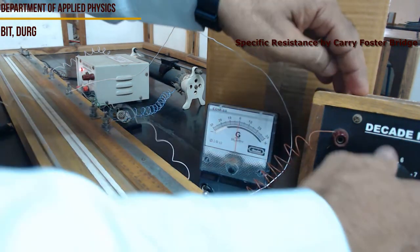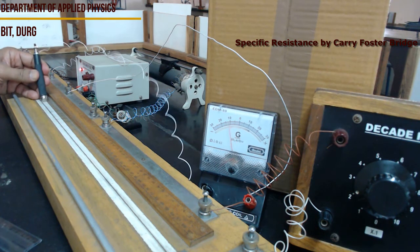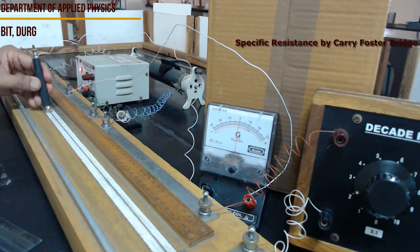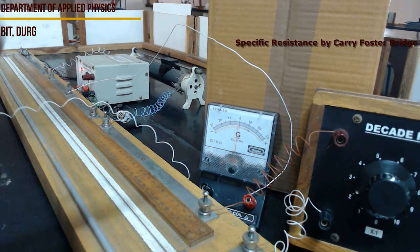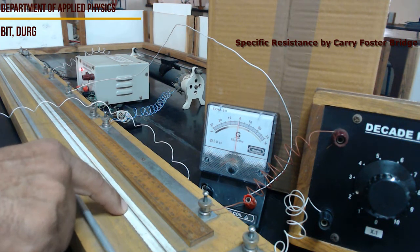Similarly, I increase the resistance to 0.2, and again I try to find the null point, and you can see I get the null point somewhere here. See, this is the null point, and it comes around 59.5. So by doing so, again I start taking readings for 0.3 ohm, 0.4, 0.5, 0.6, 0.7, 0.8, 0.9 and 1 ohm. So that will be the complete process for determination of the resistance per unit length of this specific bridge wire.